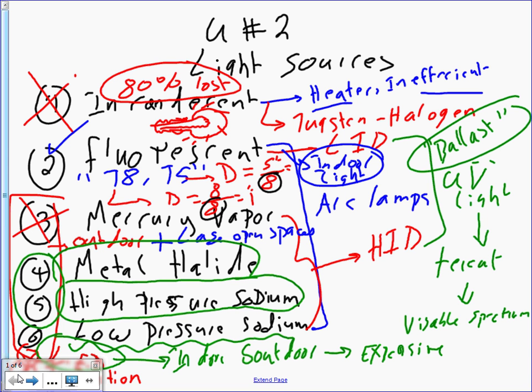If you look at page 19 at the bottom, lumen and life characteristic of mercury vapor. After 24,000 hours, the percentage of lamps still burning, this is for mercury, is 60%. So 60% of the fixtures will be burning after 24,000 hours.